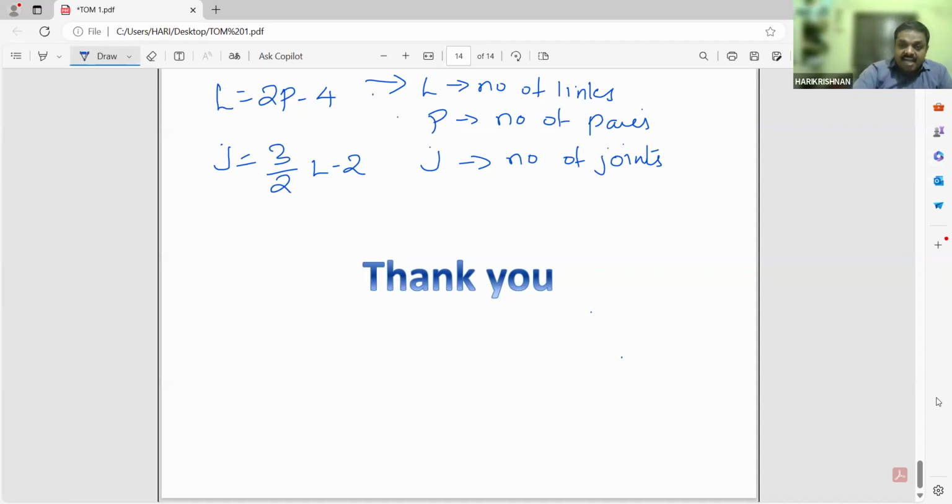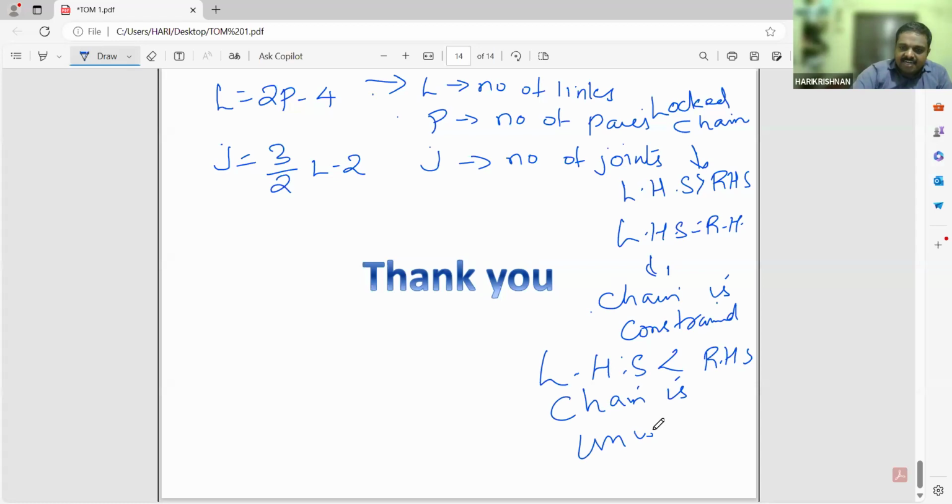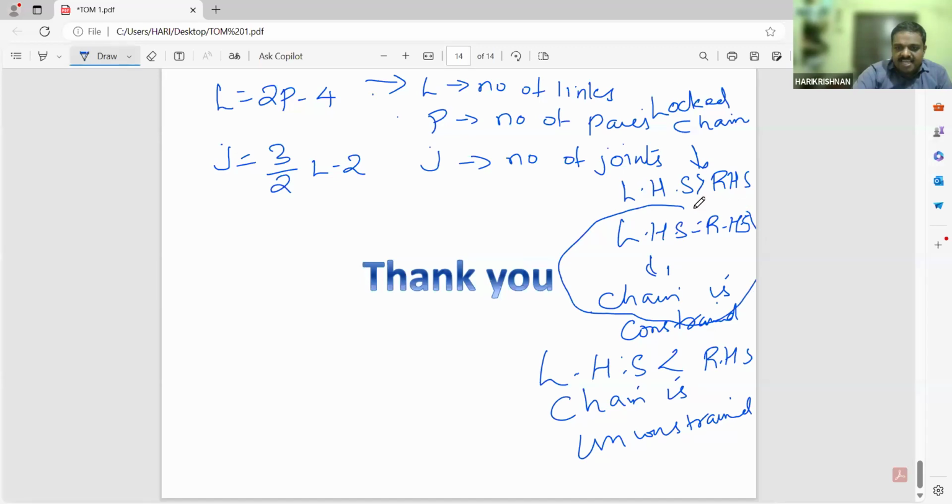So you have to understand the concept. If LHS is greater than RHS, this forms a locked chain. When LHS is equal to RHS, the chain is constrained. If LHS is less than RHS, the chain is unconstrained. These are the concepts. So for the chain to be constrained, what is the specialty? LHS should be equal to RHS, and then we can say the chain is constrained.